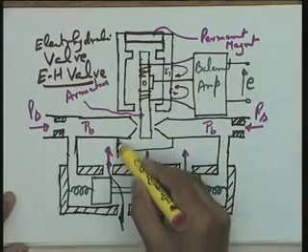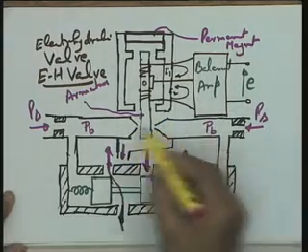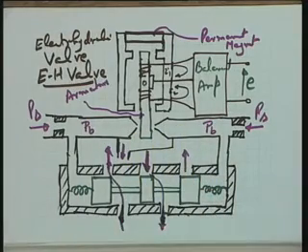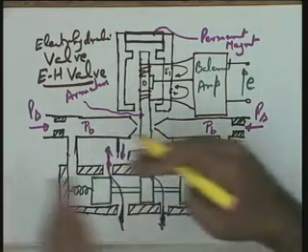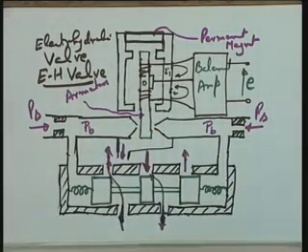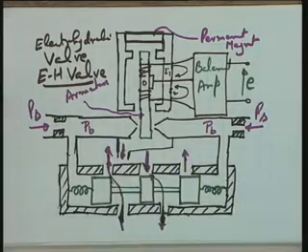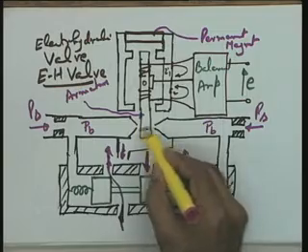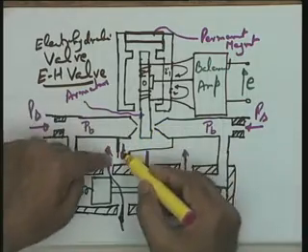Okay, whatever I have shown is the drain, because all those leakages from these two particular nozzles will go to the drain. Well, the diagram is not complete from the point of view of complete construction. This is a drain, this is a drain, this is a drain, so a common pipe can take it to the reservoir. It is only a schematic. The 3 points can be taken to the reservoir through a common pipe. This particular drain is only to take care of the leakage. This point may please be noted, the leakage through these particular nozzles.